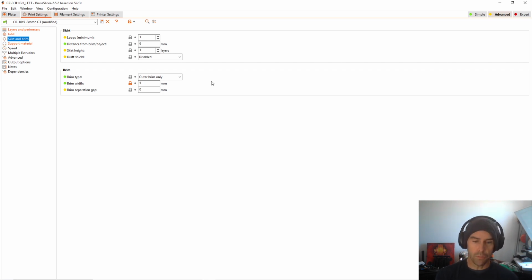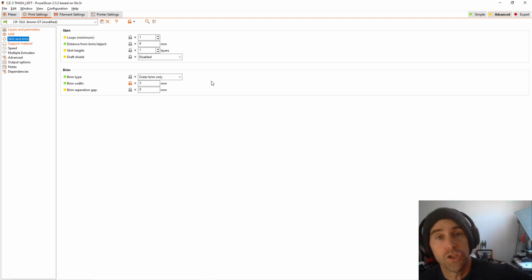But if I haven't used it in a little bit, or if I've done a big print, sometimes a big print will affect how the springs are working. So sometimes you need to dial it in. The brim is great for that, because it'll start printing that brim and you can watch it. If it's too tight or too loose, I can reach under the bed and adjust it a little bit. This is because my printer does not have auto adjust on the nozzle.